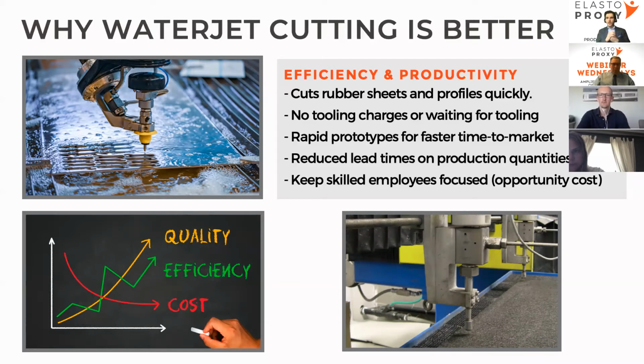If you have a couple of hundred parts, die cuts, again, depending on what you're cutting, some toolings are not expensive whatsoever, and some toolings for die cutting could be quite costly depending again what you're cutting. But you have to take that cost into consideration. Advantage of WATERJET cutting is that there is no tooling. So it's for rapid prototyping, or if you have to go into market really quick. Basically, we go from a CAD design straight to the WATERJET machine to get that cut, and you have a finished part almost right away.